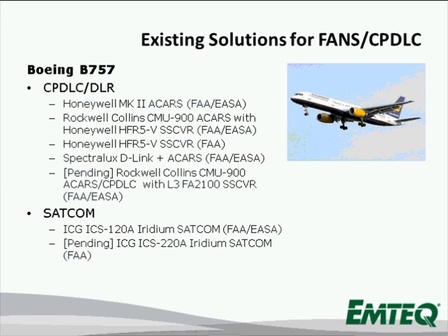And on the 757, we've done several different types of ACARS systems. Some of those were for CPDLC. Some of those can be used as baselines for FANS or CPDLC upgrades. This isn't to say that the existing systems certify CPDLC, but they can be used as a baseline. And EMTEQ can also work to develop STC amendments with a custom configuration for an operator's aircraft to certify for CPDLC. So we worked with everything from the Spectralux and the Honeywell systems to the Rockwell systems, and then a variety of the CVR types as well.